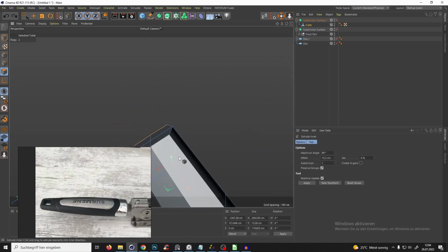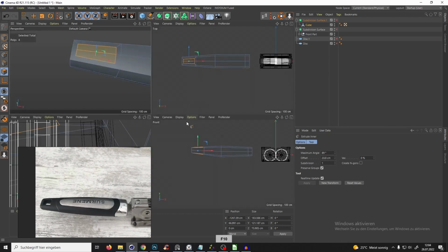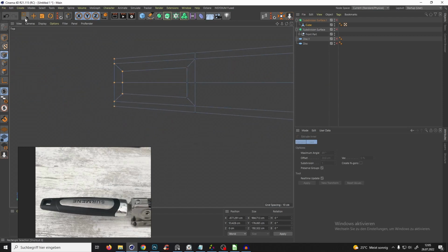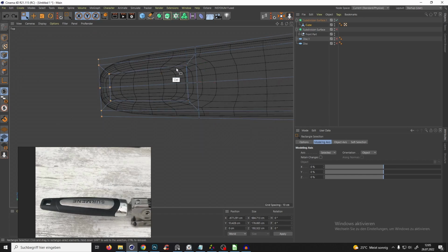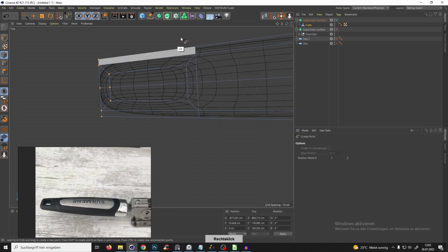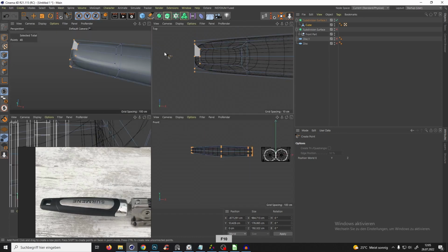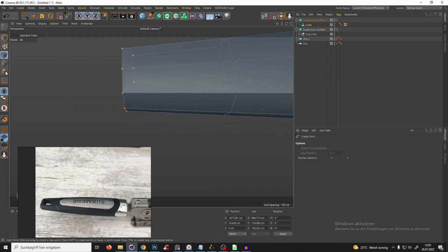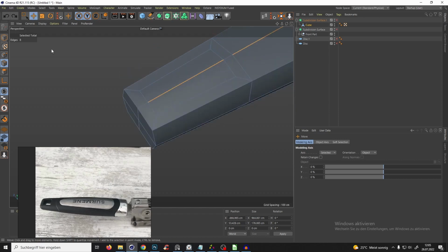So we just select them on both sides, and I for inner extrude, something like that. And we go to top view, and we just bring those points here just a little bit more inside. Well, we have to do it differently. Why is it? Oh yeah, sorry. Something like that. We have to bring those edges here. Just Control Z to go back.